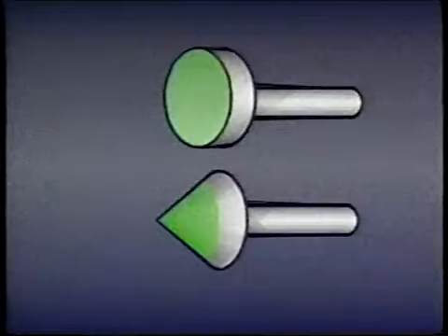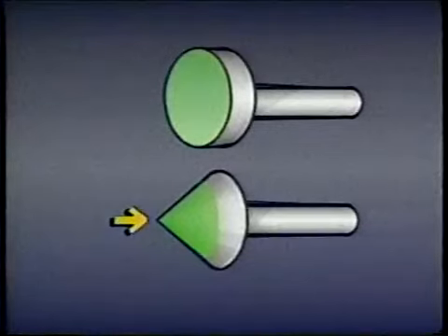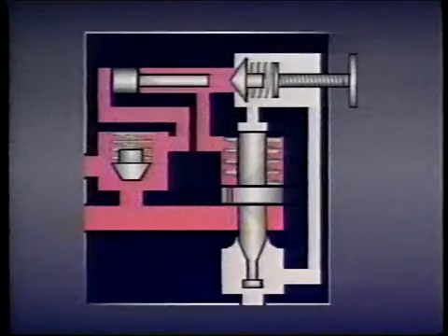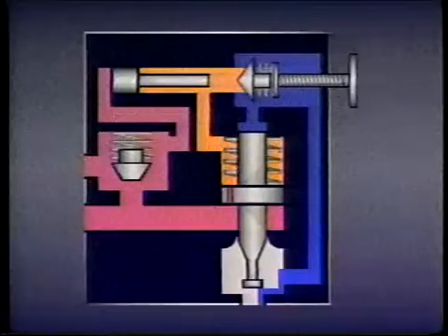The pressure differential at which the valve operates depends upon the difference between the area of the face of the piston and the area of the dart tip. Typically, the piston face is 15% larger than the dart tip. Therefore, the piston doesn't shift back until pressure on the accumulator side has dropped to 15% less than what it took to open the dart in the first place.